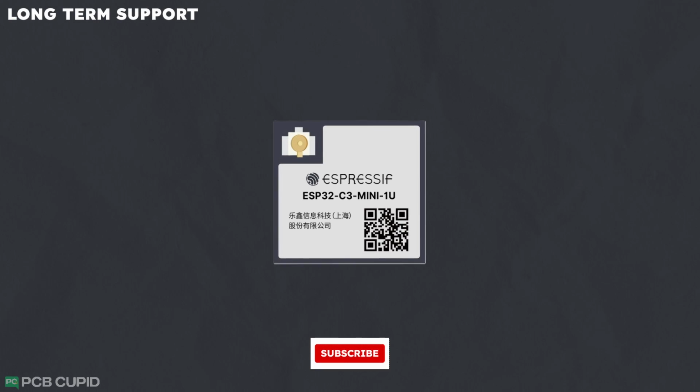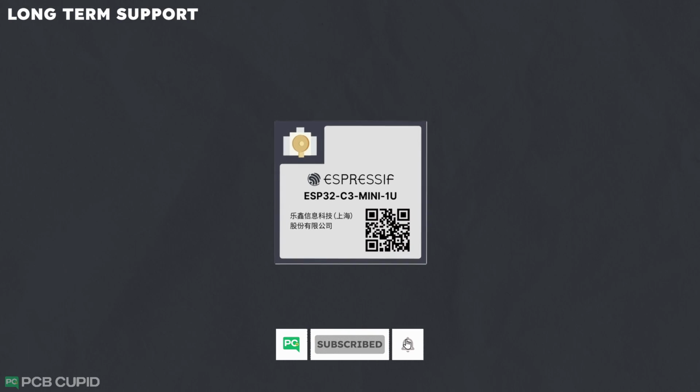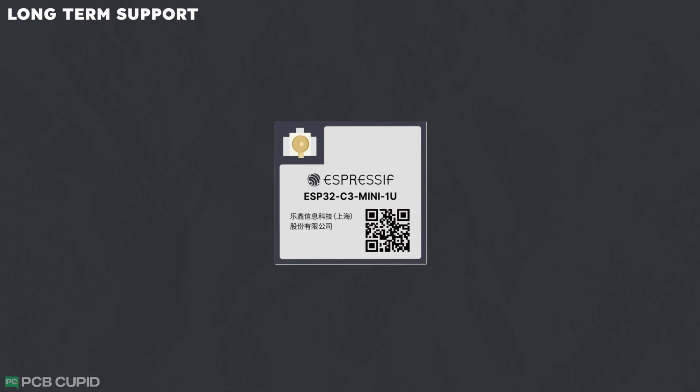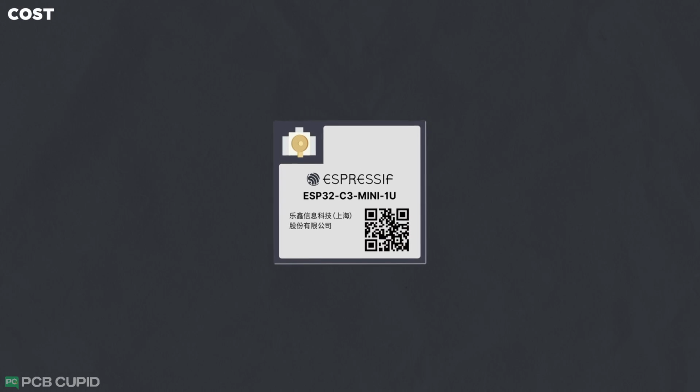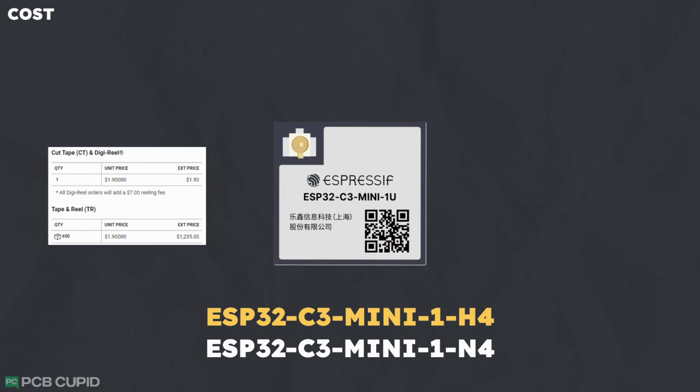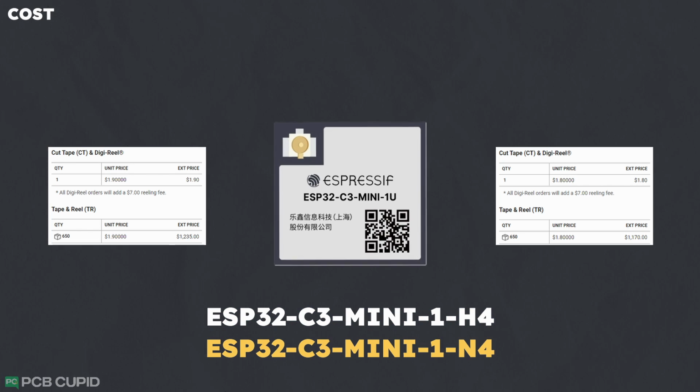For the long-term support, I'm not going to worry much, because I'm not planning to manufacture this in a large quantity or sell it for a long period of time. Finally, for the cost, this ESP32C3 Mini without the antenna version again comes in two different variants. One with a higher temperature rating for industrial application and the one with a lower temperature rating for commercial application. But I want the device to be very robust and be used in multiple outdoor situations, so I chose the industrial version of the IC.